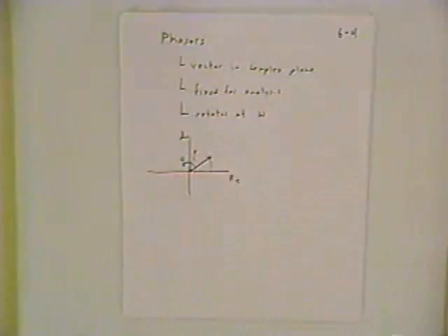And so in fact, if I look at my pen here as the phasor rotating, imagine that it's rotating around. Now I have to think through this. I want it to go counterclockwise as you're looking at it. So I'll go clockwise. And as this pen is rotating around and around, follow the tip of it. But I'm going to continue that rotation, but now I'm going to do it in a plane so that now all you can see is the tip. And the tip is oscillating back and forth. If I just project the tip into space, it's going back and forth like this. It's tracing out a sinusoidal waveform in space.